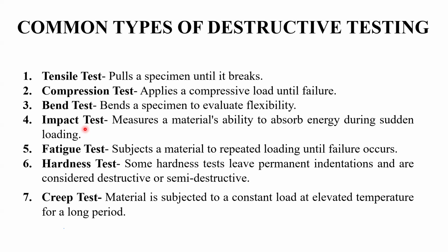When it comes to the fatigue test, both compression and tensile loading happen on the material for a period of time, like 25 times per second, in order to know whether it is going to withstand fatigue. Hardness test is where we put a dent on the material in order to know how much hardness it has.